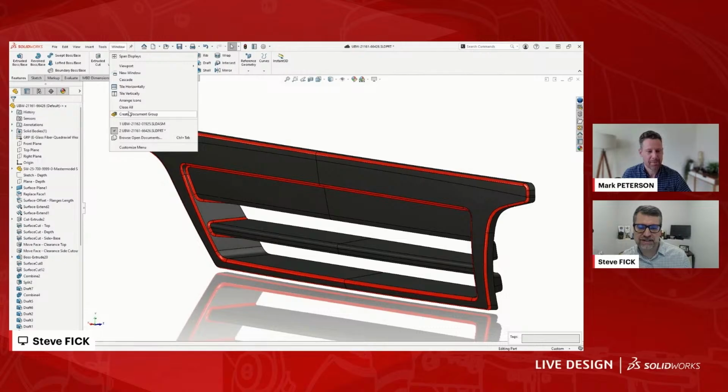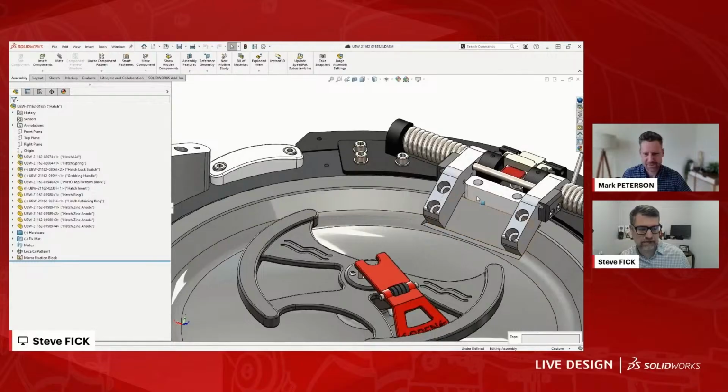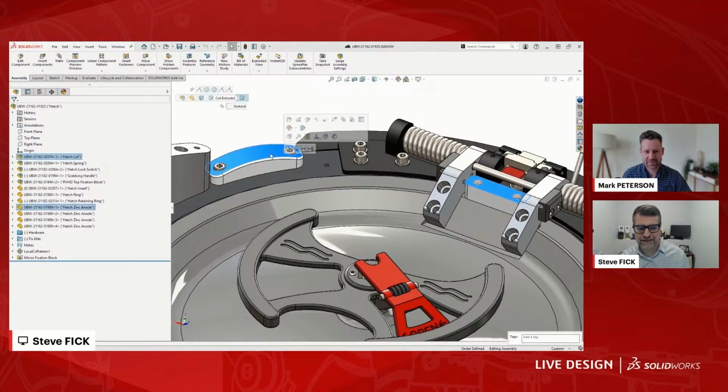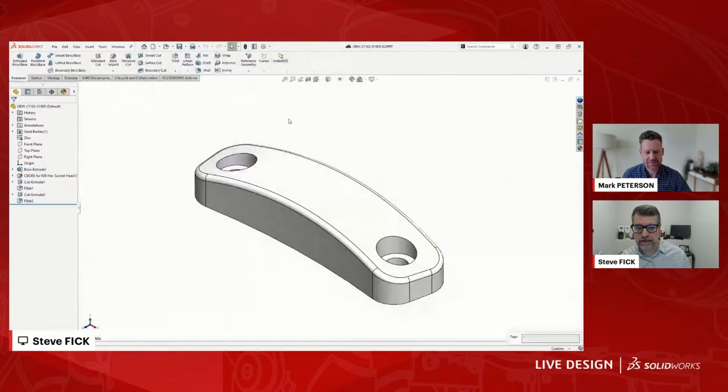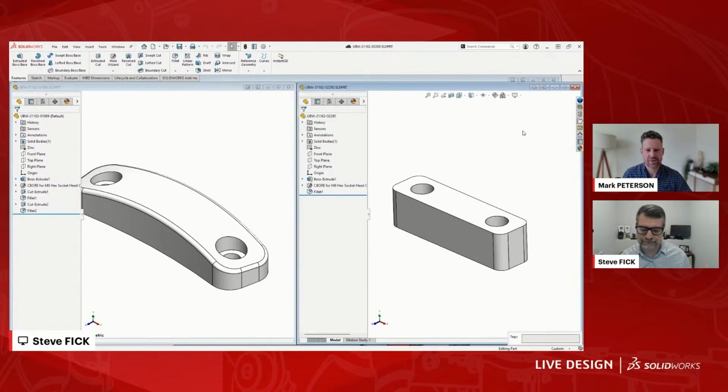So let me show you one other use case for this, and that is that feature paint will actually work across parts. For instance, maybe I've got an M6 here, and I know that there's an M8 over here. Mark, this is one that I don't know if I forgot or I just didn't know: if you control select 2 parts and you hit open, it will open both of them. And then you can use the little sorting icons over here to stick them side by side. I may have forgotten that, but that's really handy. Nice, little window management. Yeah, exactly.